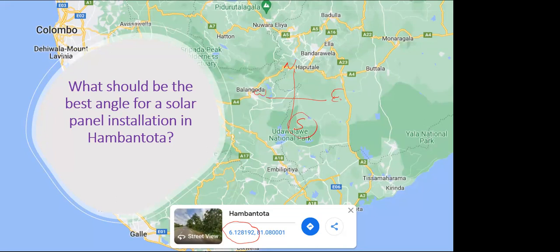Somebody can explain that it should be south to north, because the sun is coming from east to west generally. Then actually the face should be south to north, no? When we're going to fix the solar panel, this is the latitude angle. What should be this direction? This is the point that I asked. Is it north or south? It has to be due south.